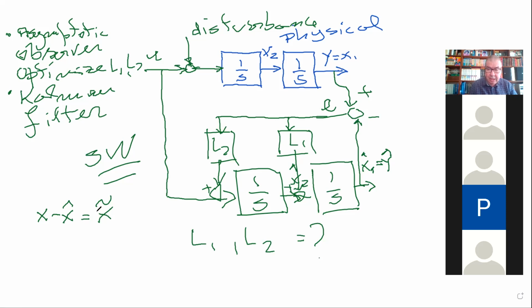That's controllability. And also, I want to estimate the system. So one thing is to design the state estimator or the asymptotic observer. These mean exactly the same. And one thing is to design the state estimator, and the other thing is to know whether it is possible to design the state estimator. That is related to the criteria of observability. Okay?